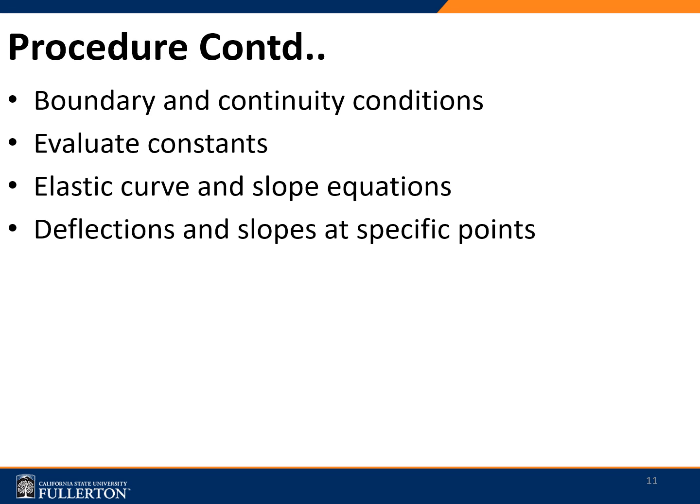So you use the boundary conditions and the continuity conditions, determine the constants, and then we can determine the curve or the slope of the bending beam.